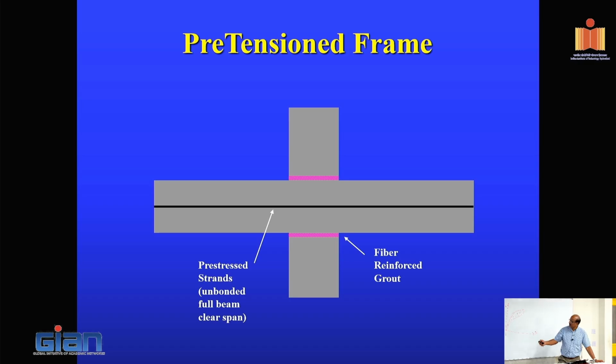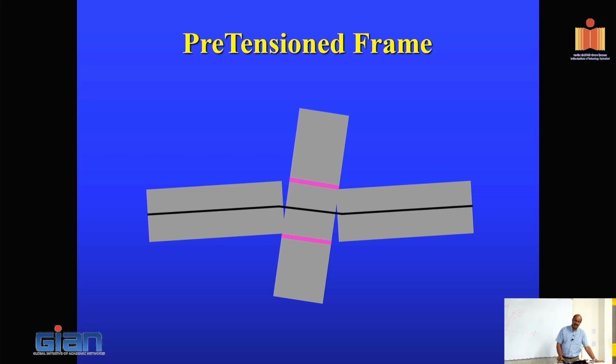They're connected with a grout pad here, and they had couplers here. We kept talking about how we don't want to use couplers, but in this case, it was designed to open at this interface. If this is not a critical path for the energy dissipation, and you put couplers, there's no harm in doing it. So the couplers were used to establish this connection. What they envision is that if you displace laterally, that's how it's going to open up.